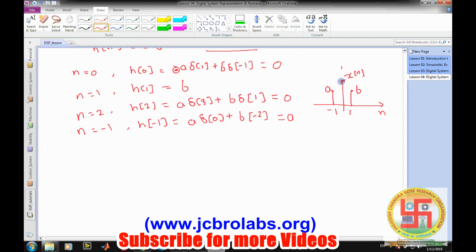Now if we check the absolute summability, n equals minus infinity to infinity, mod of h of n, because we have to sum all the sequences, it will be simply a plus b, right? So it will be absolutely summable if a and b are both less than infinity. So this term will be less than infinity, and then this h of n will be absolutely summable. So the system is stable.